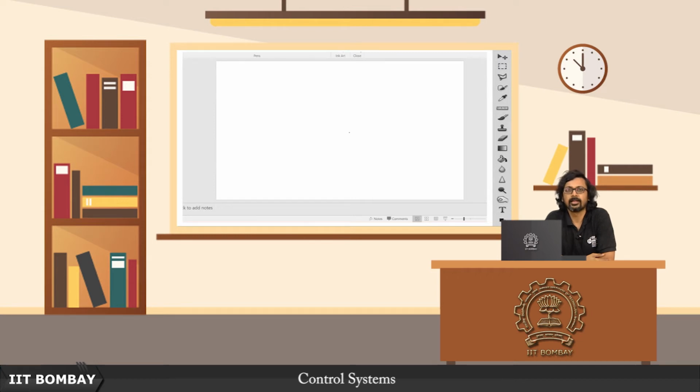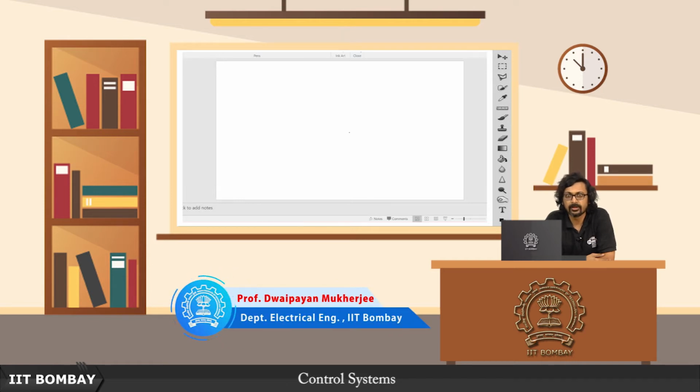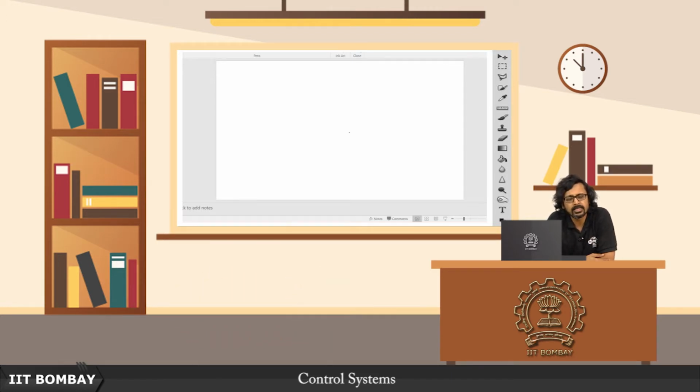Hello and welcome back to the final lecture of this course on control systems. Over the course of the last lecture we have seen, with an example, how to design a state feedback controller for a plant which would otherwise not even be stabilizable using proportional or proportional derivative control action. So we have seen that at least in principle, if we are allowed to tap into the states of the system and use linear state feedback, we should be able to stabilize it. Not just that, we will be able to place the closed-loop poles of the system at any location of the complex plane that we desire.